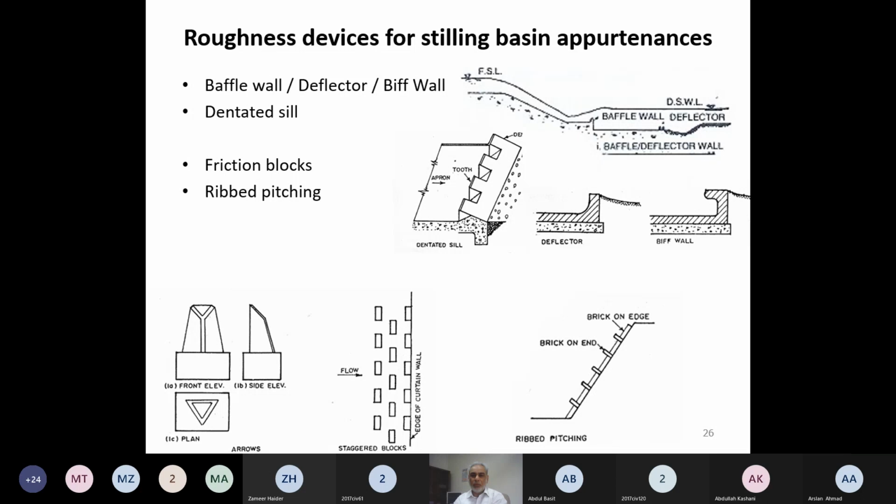Barrages are also similar. On the upstream side, usually we have the ponded water, we have the high water level. On the downstream side, usually we have the low water level. Except in the flood condition, we have nearly similar water levels. But in the dry condition, when gates are fully closed, a huge water level difference is there. And if we want to open the gates, then water will fall from the high head to the low head.